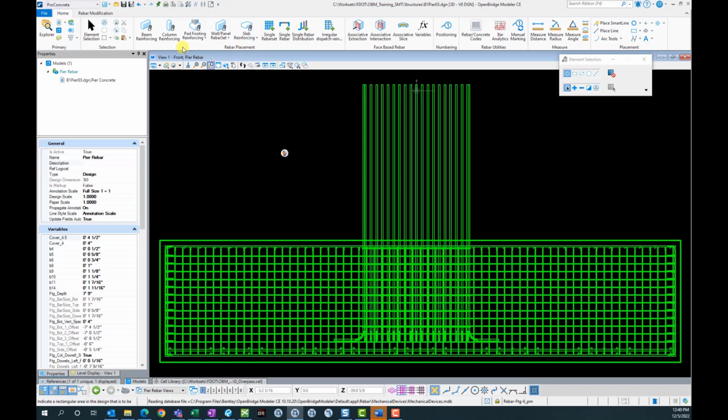If you have a perfectly square or round column, or a square, rectangular element, you can use the beam reinforcing tool. But in general, I typically avoid these unless, again, the geometry is very simple, which is what those element-based dialog boxes were built for. Now, the second workflow for modeling rebar, which is what we'll use in the bridge role, can be broken up into 2 different categories of itself, like an A and a B. And this is using the custom reinforcing tools here.